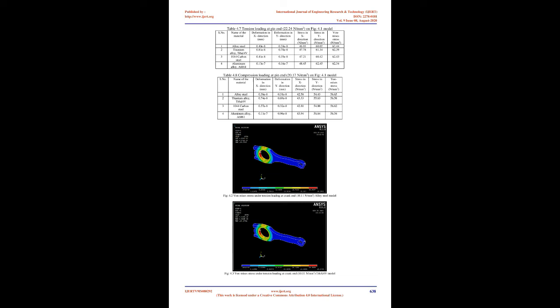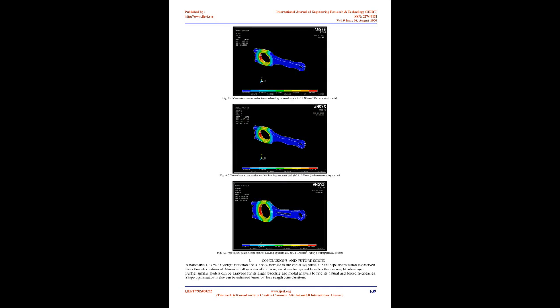3. Model development and strategy. A typical connecting rod is modeled using AutoCAD software and imported into the analysis software ANSYS 08, used to simulate engineering models to extract displacements and stresses. A solid brick element is chosen for meshing, and different loading conditions, tension and compression, were considered at the crank end and pin end.